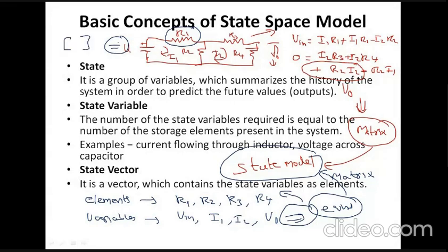Using KVL or KCL you write the equations, then represent those equations in matrix form. Two steps: first write the equations, second represent them in matrix form. That will give you the state model.